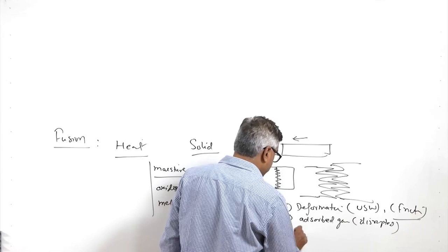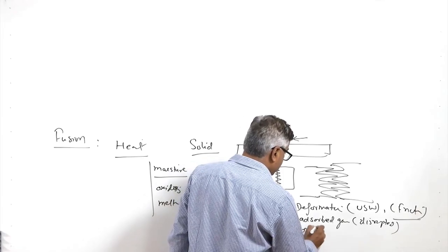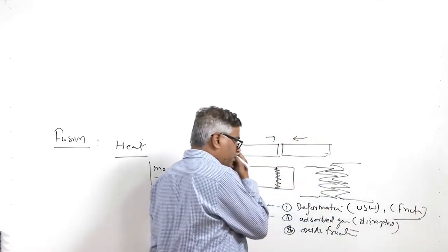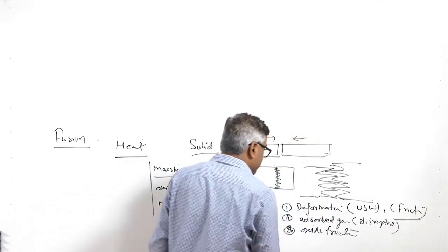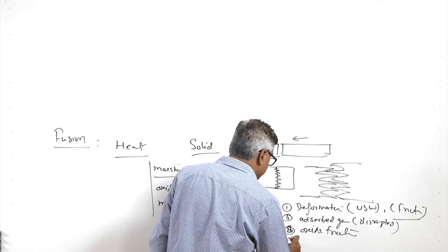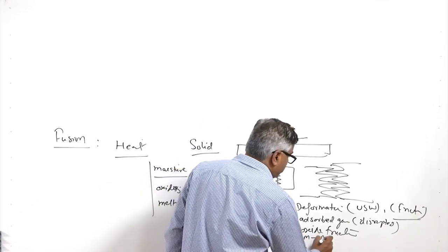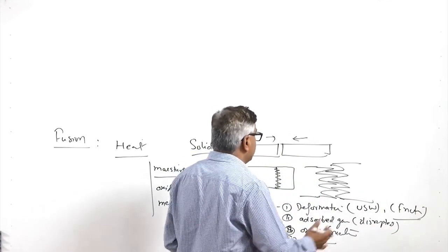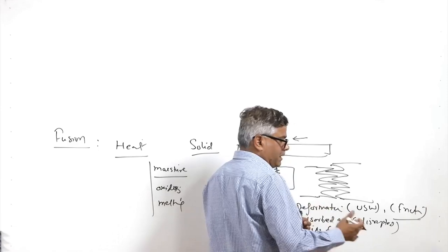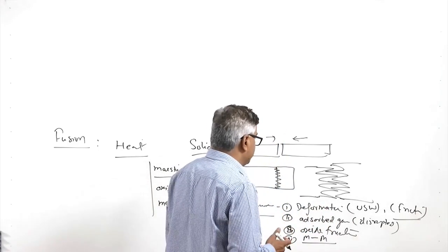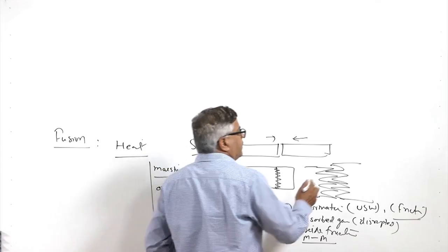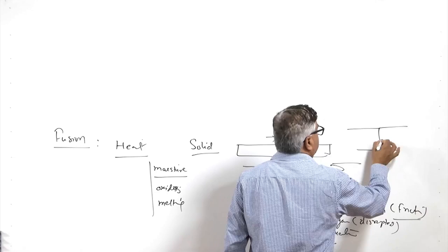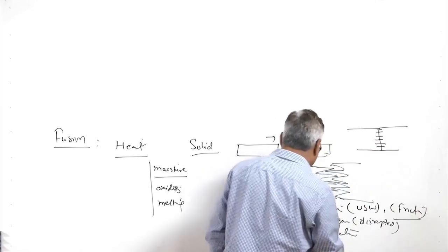Oxides are fractured due to the micro level deformation which will be occurring at the surface. So, all these things will be increasing the metal to metal contact between the components to be joined, and once that is there, then we will have the metallurgical continuity. If the two components are kept under pressure for certain time, then the metallurgical bond is established.